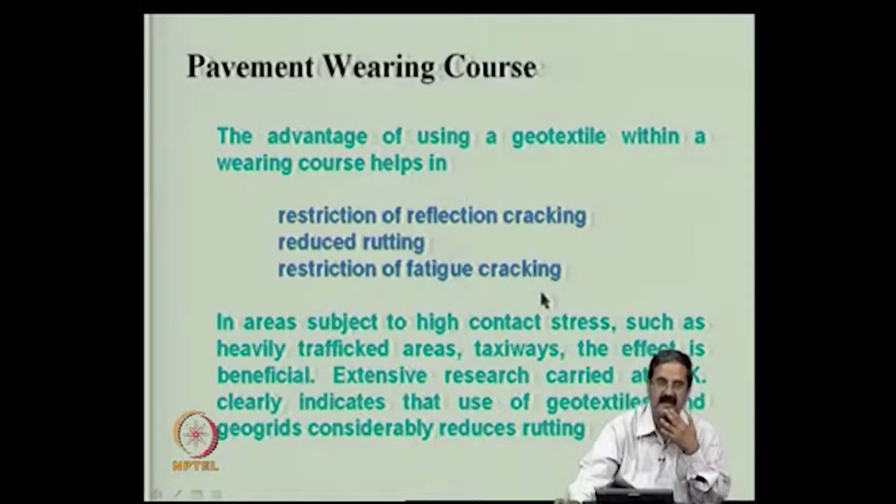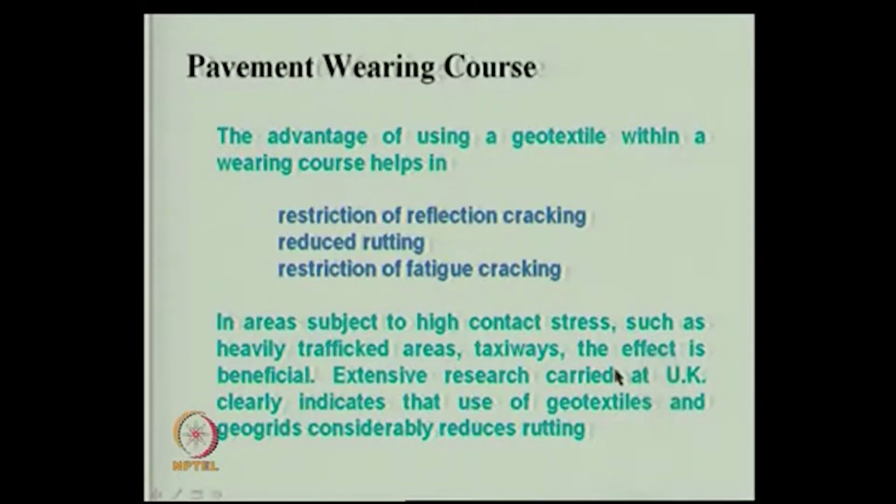Restriction of fatigue cracking: because of the alternate or repeated action of loads, the fatigue cracks do develop, and in areas such as high contact stresses, heavily trafficked areas, taxiways, runways and all airfield pavements, the effect is beneficial. In fact, a lot of work has been done in the UK and other places, where they clearly show that the use of geotextiles and geogrids considerably reduces rutting.